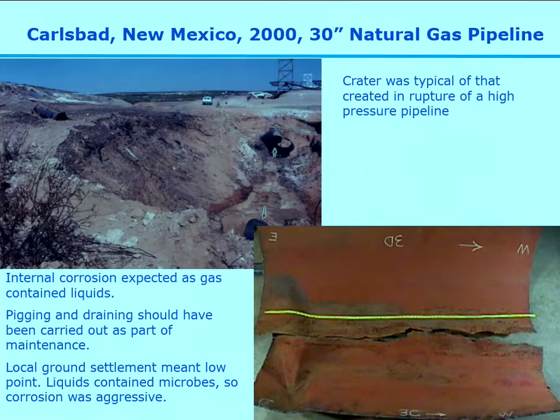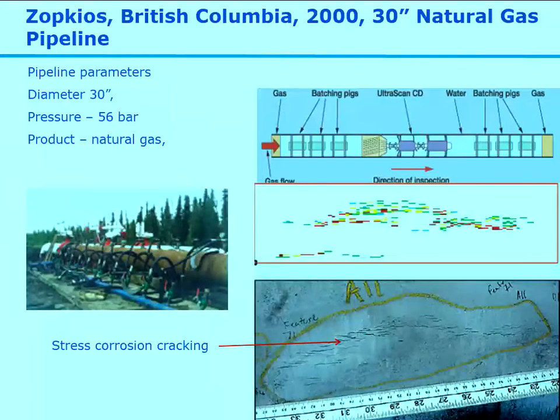One of the issues in terms of corrosion which is causing concern at the moment is external stress corrosion cracking. This causes major concern because the cracking occurs as tight populations of crack defects. They're often very short and not that deep, but they are very, very sharp, and because they occur over an area, it completely reduces the strength of the pipeline in that area, and because they're sharp, they're essentially crack-like defects. So it's a very aggressive form of corrosion, which you can see there.